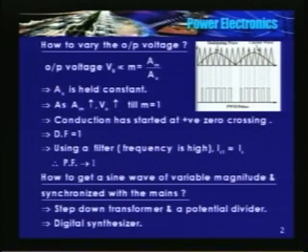There are a large number of pulses, so the frequency of the predominant harmonic also increases. So I use a small L and C which filter this predominant harmonic. It so happens that the fundamental component of the source current is approximately equal to the RMS value. So the power factor also improves. So the power factor of a PWM converter is approximately 1, unity.